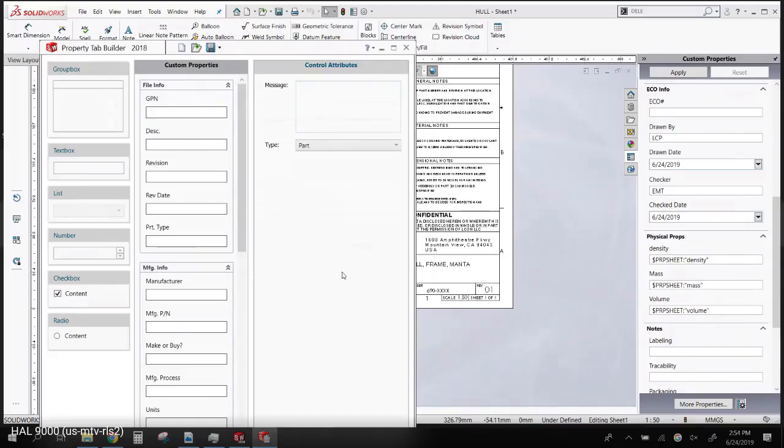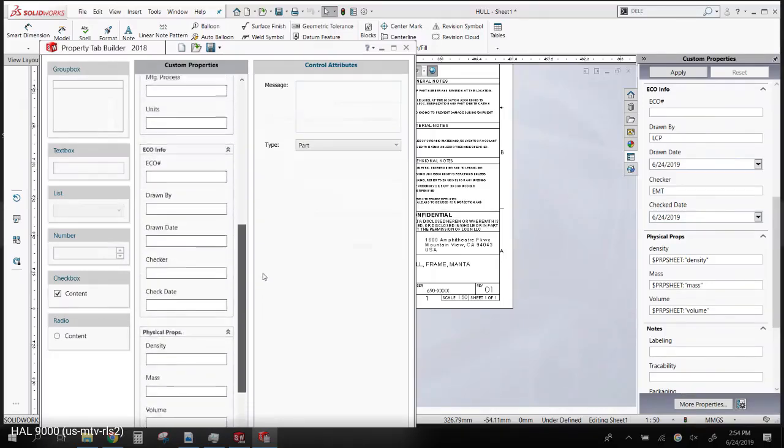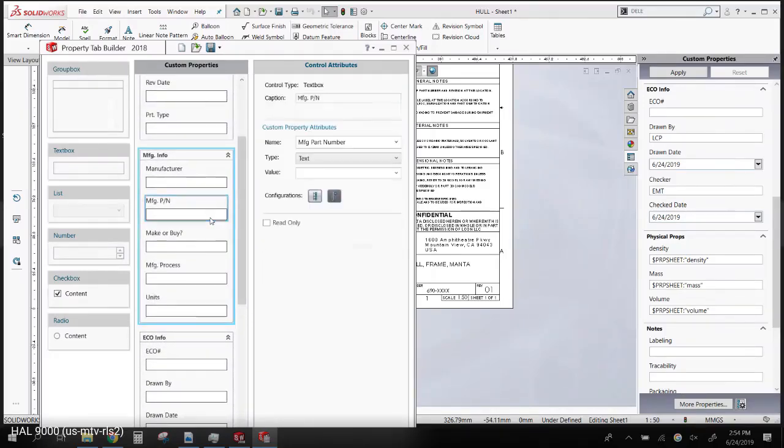It's actually in the Loon library in their vault, but here's all the information, and you can see what it's filled out for. You need one for assemblies, one for drawings, one for parts. Set up whatever metadata is important in those, and then you can do like I did. Just go to that tab, start typing information in, hit save. When you check it into the vault, I already know it has all the metadata because I filled it out.